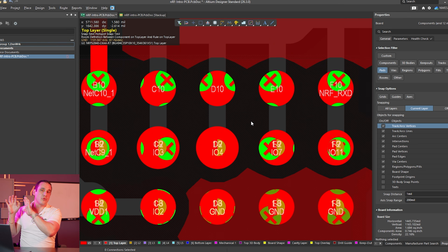But this is something that you would normally control inside of the footprint. You can, of course, change it inside the PCB layout if you want, but a good idea would be to go back to the original footprint for this component, select all of the pads, and set them to rule expansion rather than manual expansion. And that's going to allow you to then control what is the pad mask expansion directly from the Design Rules and Constraints editor using the within room query.